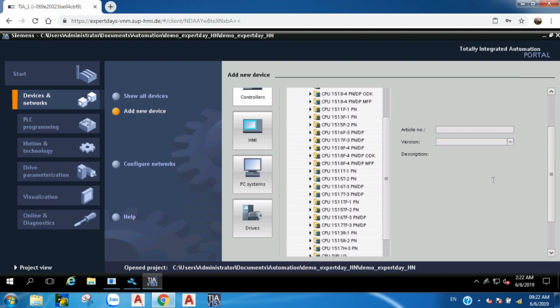You can also do it in the control panel setting or the comfort panel. Of course, please be reminded that those messages are saved in the internal flash memory. So if there is a high number of alarms, the internal flash memory will be stressed more. So if important messages are located in the archive anyway, please disable and switch off the persistent message buffer setting.